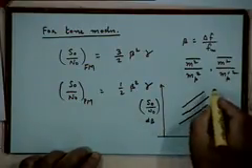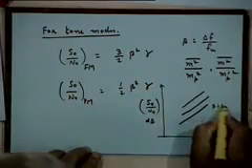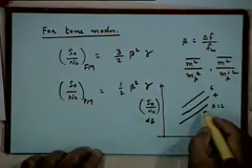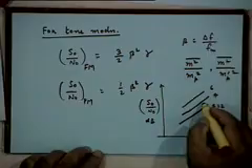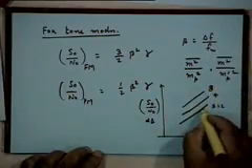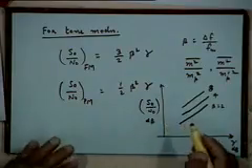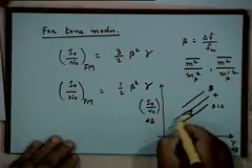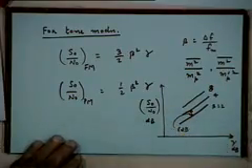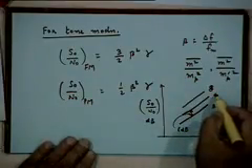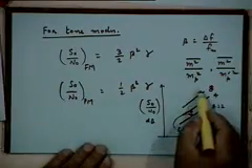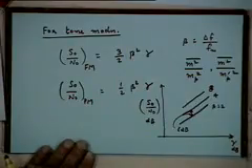For example, this could be for beta equal to 2, for beta equal to 4, for beta equal to 8, etc. As you know, for every doubling of beta, which means doubling of bandwidth, the output SNR will improve by 6 dB. So this gap is 6 dB. As you go from beta equal to 2 to beta equal to 4, the curve goes up by 6 dB. Similarly, when you go from 4 to 8, the curve again goes up by 6 dB. That's something you must know.